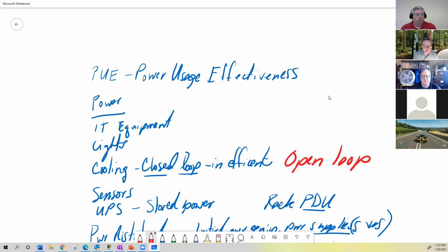And so yeah, you've got to have enough airflow. The hotter it is, the fans detect that on the server. There's a sensor on the motherboard, and it'll kick in the fans and increase the RPMs to blow more air across your components to cool your server and your processor. When the air is hotter, it needs more airflow. So that's something else to think about.